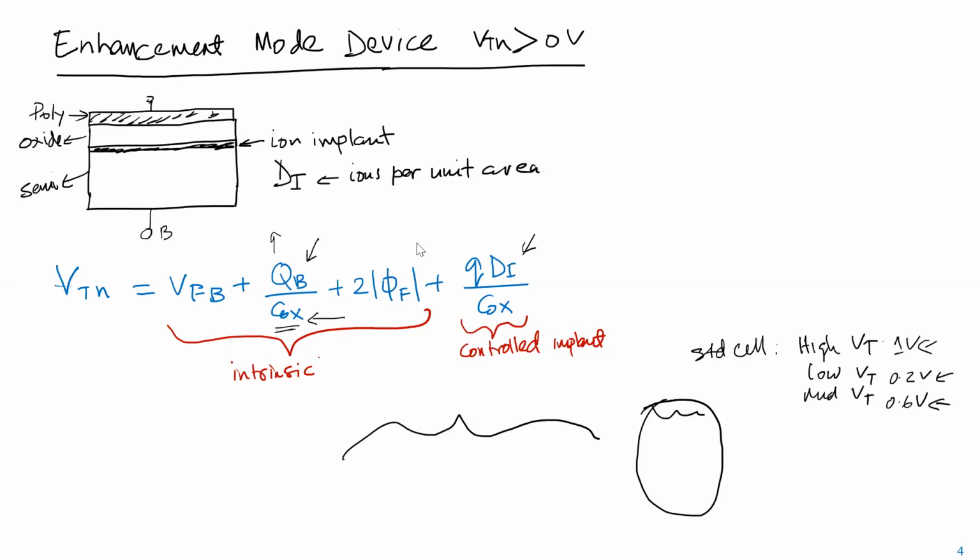But you're right. So I think maybe I didn't make it clear. When I'm talking about controlling the VT, I'm fixing the VDD. For a given technology, for example, there are two scalings, right? Let's say 0.18 micron technology. If I take the LVT device, that will be 1.8 volt VDD, that's the max, and VT is equal to 0.6 volts, right?